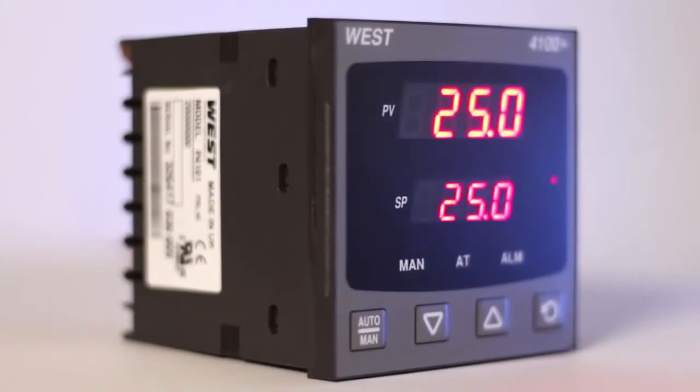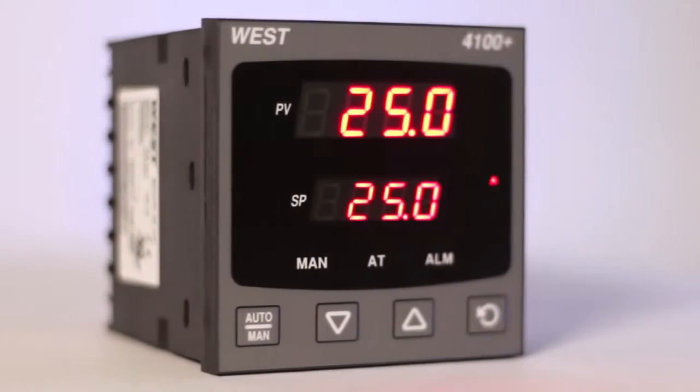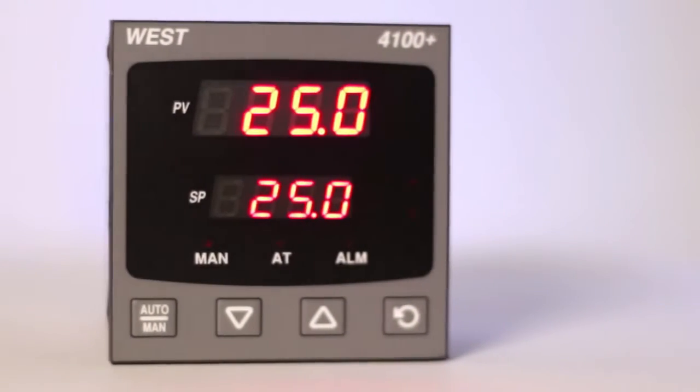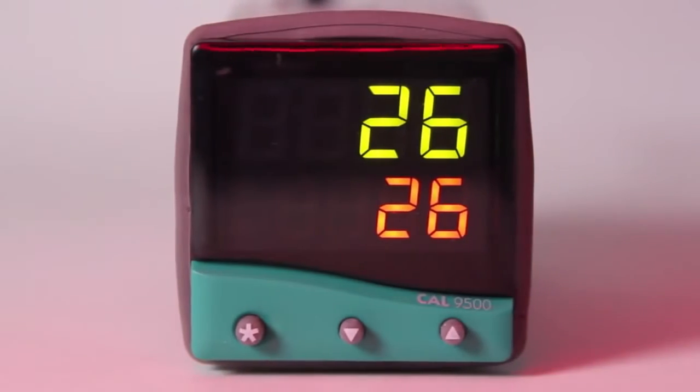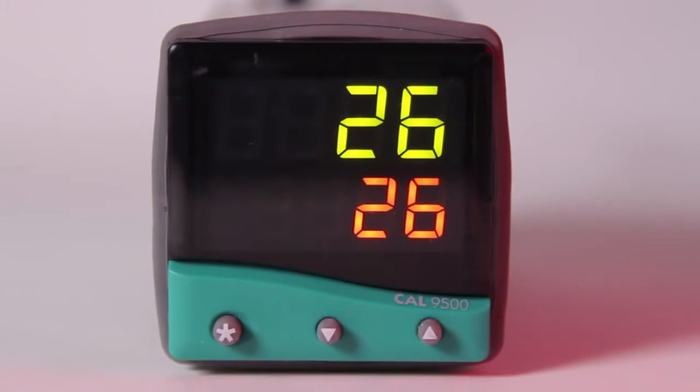A proportional controller doesn't just turn its output states to on or off, it can adjust them anywhere between 0 and 100% of available power. The direction of output is still important with proportional control. With reverse acting, the output is slowly moved from 100% through to 0% as the process rises. With direct acting outputs, the output will move from 100% to 0% as the process falls.